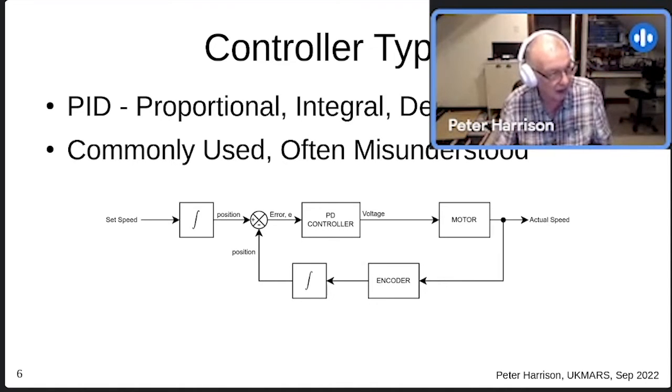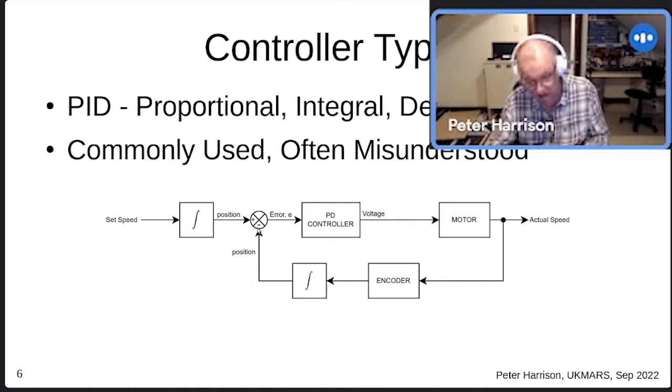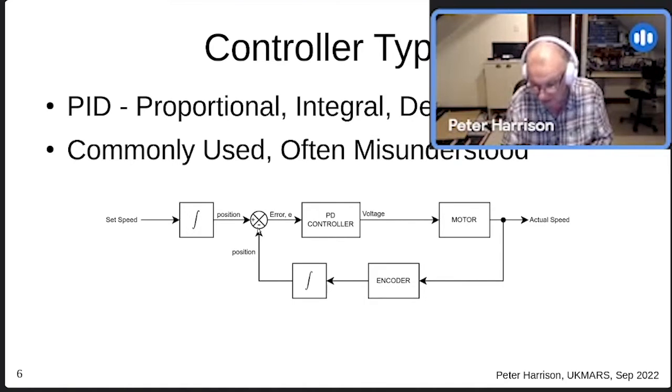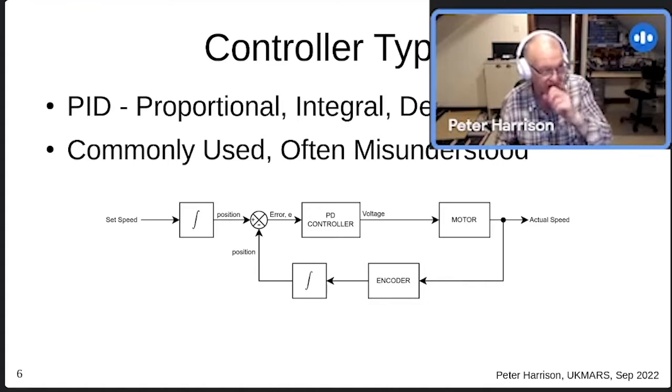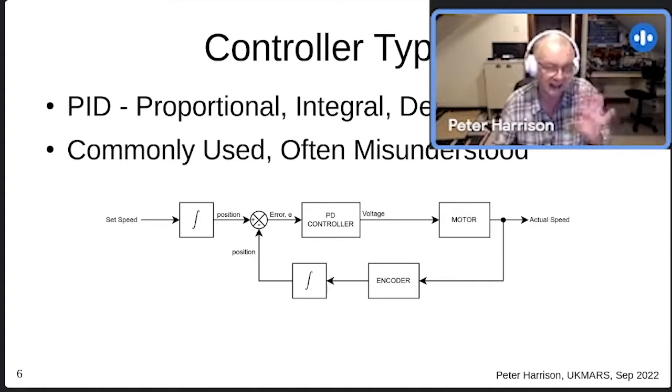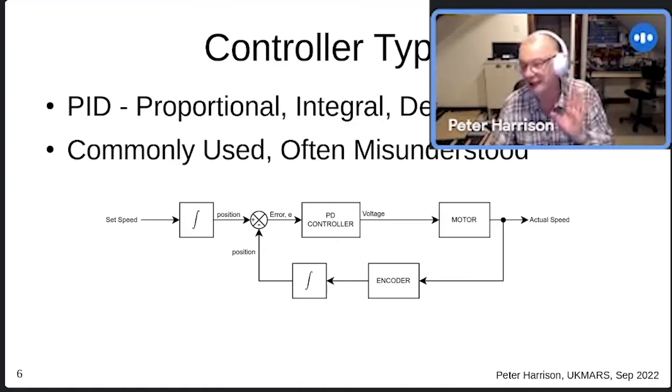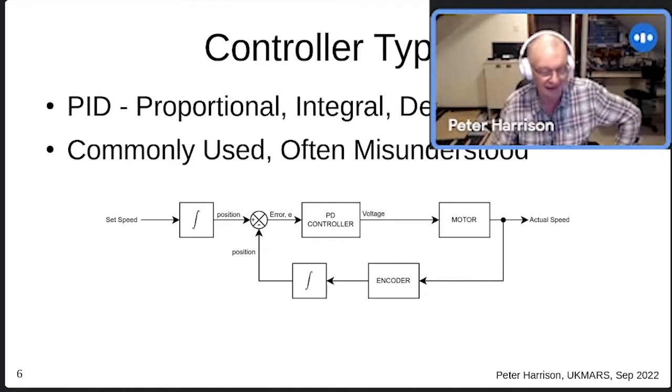The robot, however, may have moved more or less, and so I get a distance back from the encoders, and I subtract that, right? So I want my set point to move on a millimeter. The robot's only moved 0.5 millimeter. I've now got a 0.5 millimeter error, and I use that to work out a voltage to drive the motors. That's not what tonight's about, but that's what's going on, right? You'll see it in a bit, so it's worth explaining.